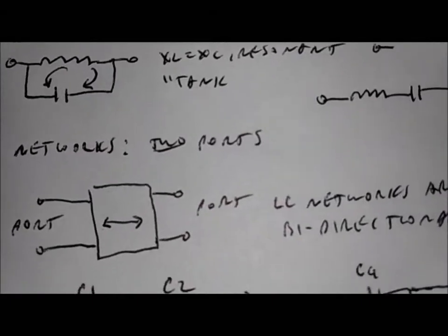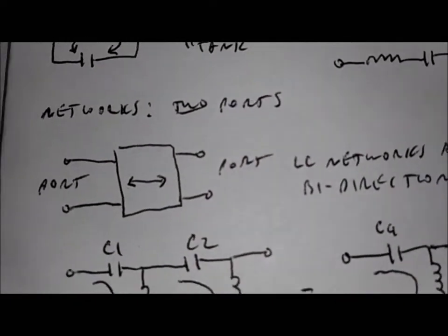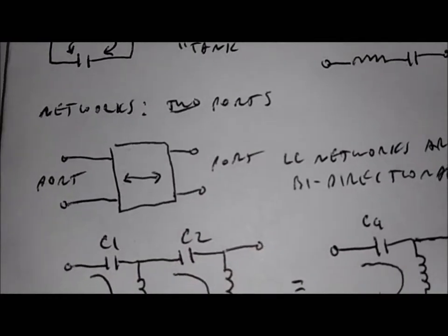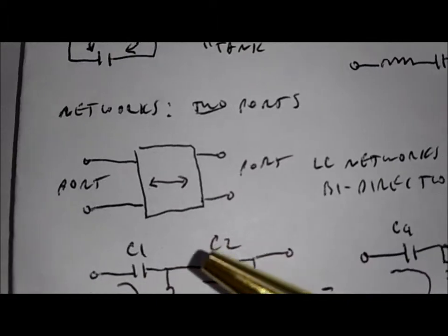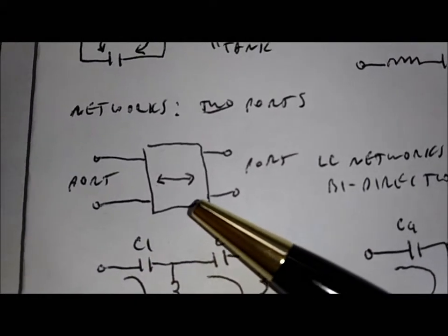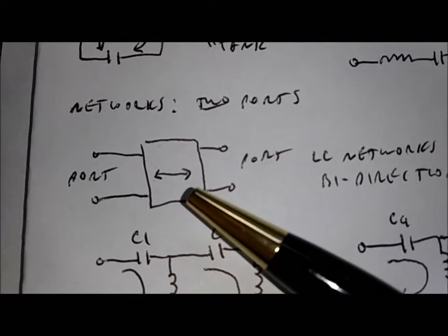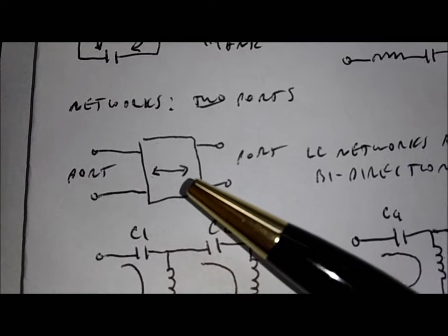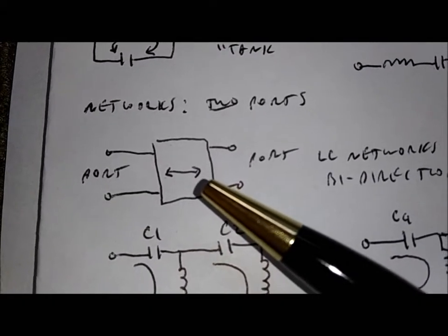Okay, networks are made of those components, generally analyzed without resistance. We buy good components, we minimize resistance, which is mostly loss. A network can be approximated as a black box with a port on each side, and very important to notice, they are bi-directional. So this baloney about magic tuners making all the reflected power from the antenna go back to the antenna is flat out BS.